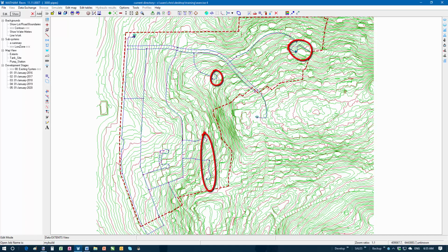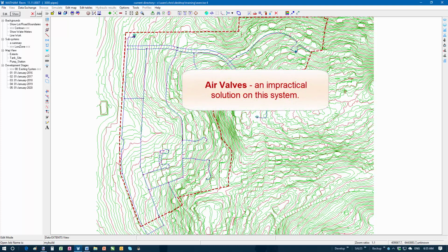That trace graph was referring to these highest locations in the system. And in the last part of the engineering mission, we analysed the effect of placing a 25mm Ventamat air valve here. It delivered a marginal improvement in minimum head in this local area, but that's all it achieved. The network operator is not likely to accept a recommendation to install lots of air valves on the reticulation pipes. It is a solution that delivers only marginal benefits while creating added maintenance and operation issues.